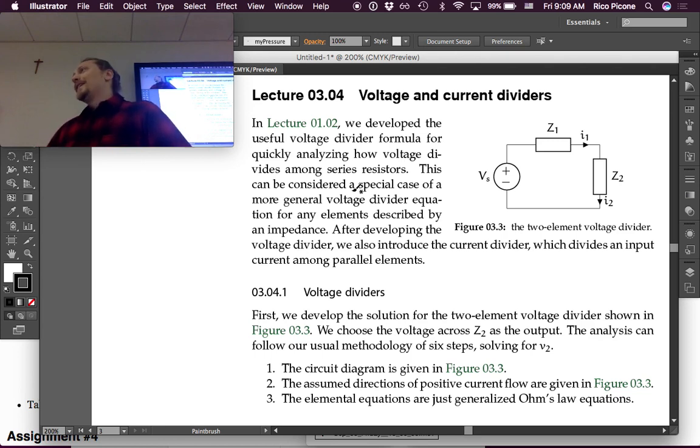It's just with a sinusoidal input and an underdamped response. If you're not getting an underdamped response, you've got the wrong solution to your characteristic equation. So it should be oscillatory, both in transient and in steady state. But in transient, it should be a decaying sinusoid. Steady state is just a sinusoid. Okay? All right.